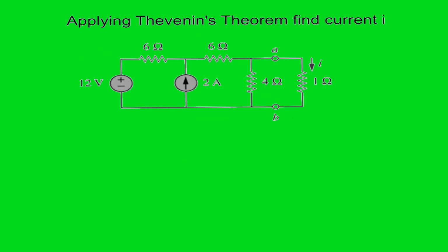So let's start finding the Thevenin equivalent, and we need to find V Thevenin and R Thevenin. First of all, we need to remove the load, because the equivalent is the equivalent at an open circuit between A and B. So once it's done, we can start looking at the equivalent resistance, R Thevenin. This will be our first step. So how to do this? How to find R Thevenin? We need to remove all independent power sources and find the equivalent resistance in the circuit.